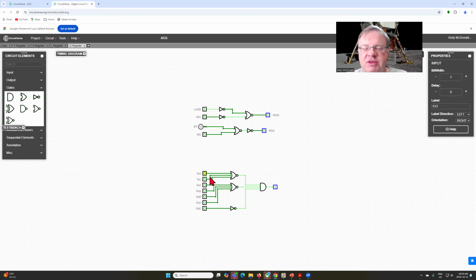The first 3 are actually fairly straightforward. You can use a shift register to just shift 1 bit left or shift 1 bit right. And then whether you carry around or not depends on whether you're doing a cycle command or the shift command. That last one, EDOP, is a little bit more interesting.